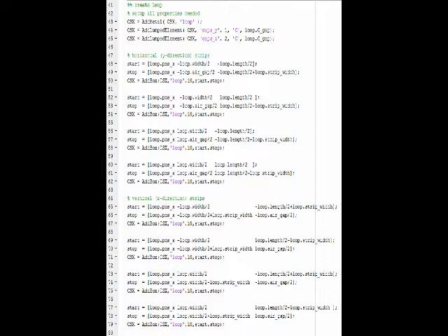In the following process, we have the loop antenna structure in the YZ direction only, in the air box. Therefore, from line 47 to line 79, we create the strips to form this whole big piece of the loop antenna. Line 47 to line 62 is the strips created in the Y direction. From line 64 to line 79, it is the strips created in the Z direction.